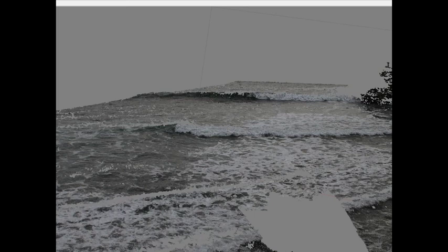Does PhotoScan allow you to calibrate the cameras in advance? Yes. If you wanted to give it a camera calibration, you could. So you might be able to do a sort of sensitivity analysis where you figure out which things are most critical to have, that would allow you to significantly reduce the number of control points and not have them so close together and not go through all of that effort. Maybe a modicum of a calibration is enough.